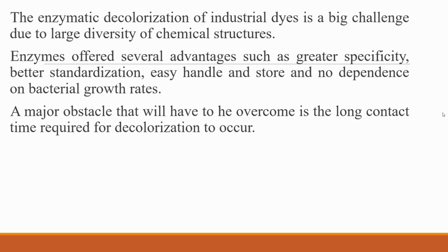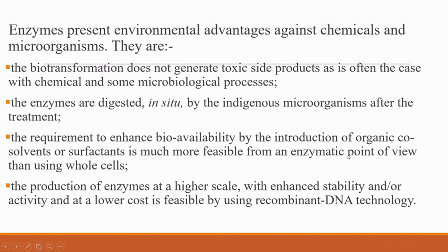Enzymes offer several advantages such as greater specificity, better standardization, easy handling and storage, and no dependence on microbial growth rates. That's one major thing about enzymes. Once they are isolated, they do not depend again on whether you're growing the microorganism or not. Now, a major obstacle that has to be overcome is the long contact time required for decolorization to occur. Remember, enzymes are soluble.